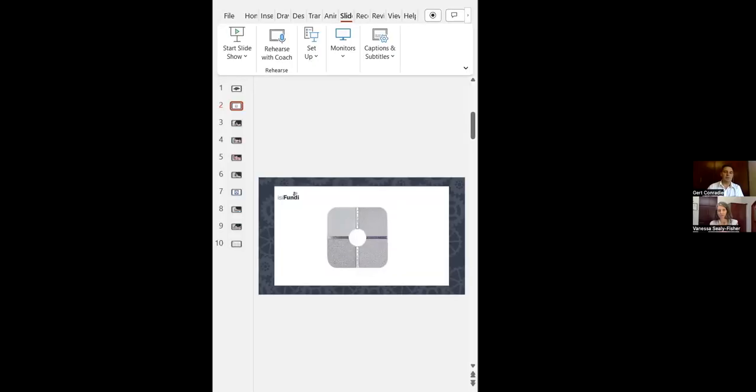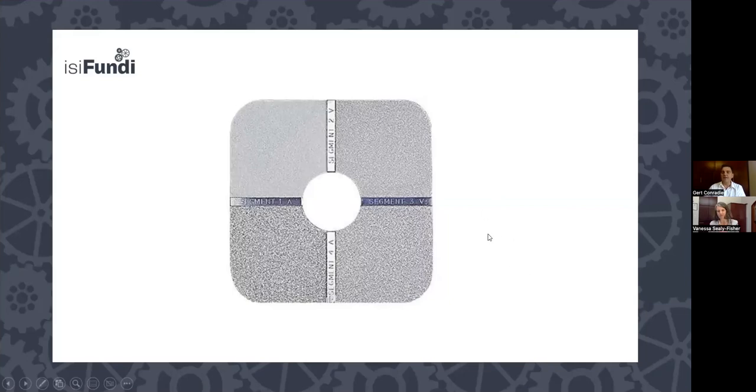Are those the only ways we can measure profile? There's actually 3 different methods of measurement. And again, I'd like to share my screen with you. In accordance with ASTM D4417, the 3 most common methods that are used is using something called a comparator. And a comparator is basically a steel panel that's more or less about 2 inches by 2 inches, and it's got different roughnesses in different segments.